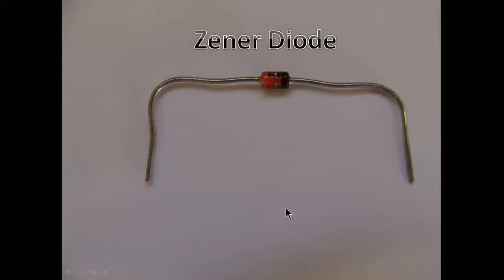You're going to do it for 3 diodes, so you're going to do the small signal diode, a power diode, and then the Zener diode. So the Zener diode looks slightly different. It's got the rounded corners, the same as its pictorial. Cathode again is indicated by, in this case, a black line. So you're looking for a line on a diode, and that will indicate the cathode.